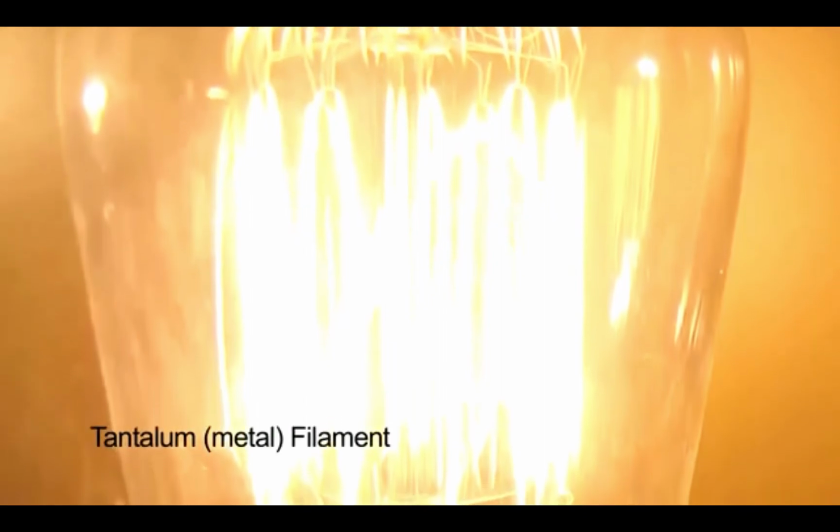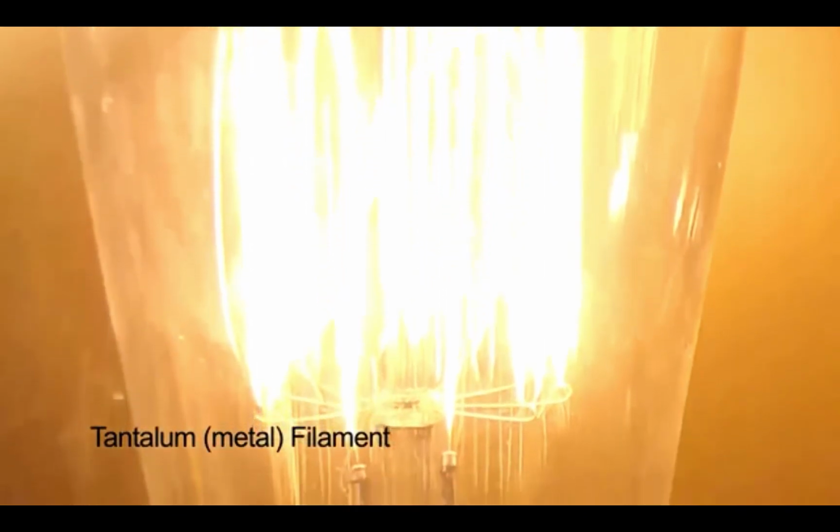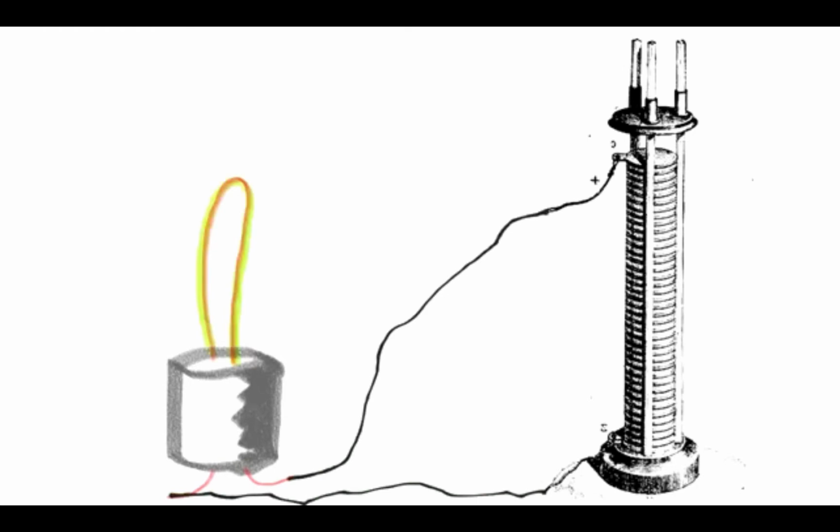And in that case, it creates photons, which is light, and also it gives off radiant heat energy as well, which is actually another form of light, infrared energy. The reason why the filament is sealed in a bulb is because if it were exposed to the air, it would burn up in a few seconds because it runs at such high temperatures. So by putting a vacuum in the bulb like the old Mazda lamp has, it keeps the filament away from the air so it doesn't burn out.